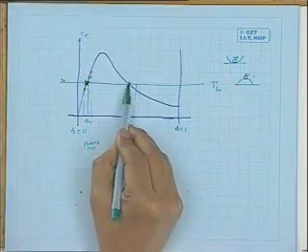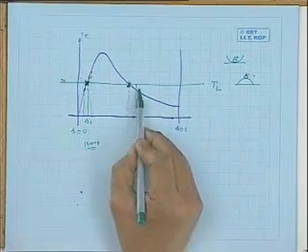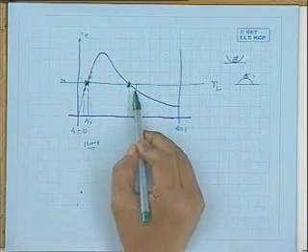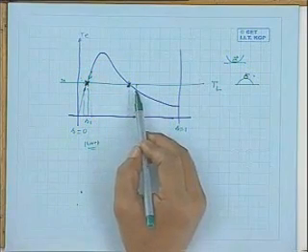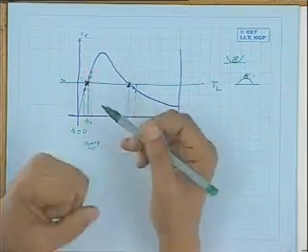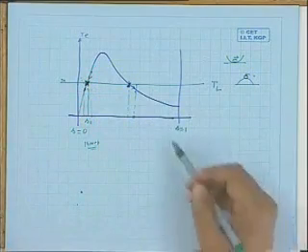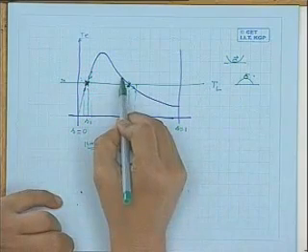Then what do we find? The load torque is greater than the electromagnetic torque. A slight shift in this operating point towards the right in terms of the slip axis will make the load torque greater than the electromagnetic torque, and then the machine will further decelerate. That is, the disturbance in this direction will further pull the machine down to zero speed.